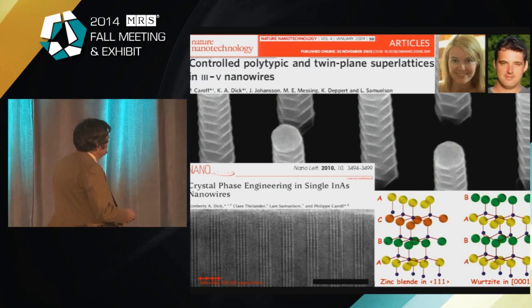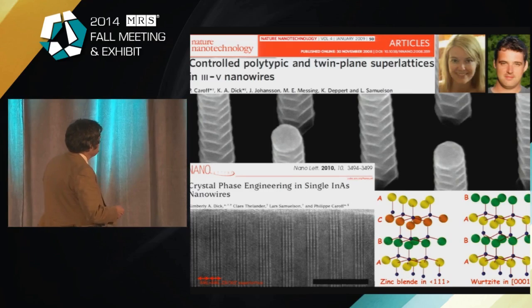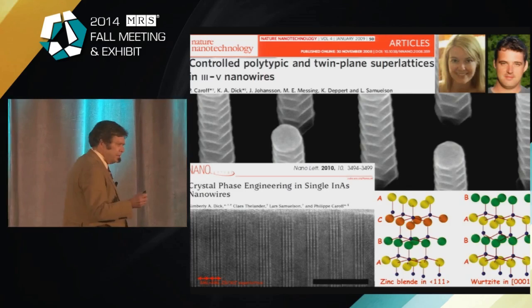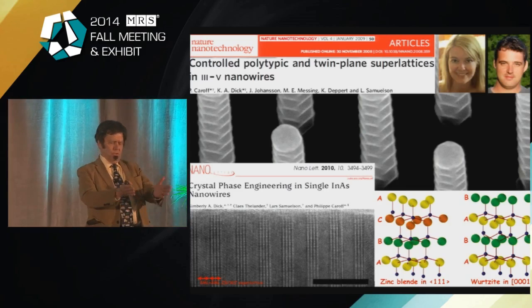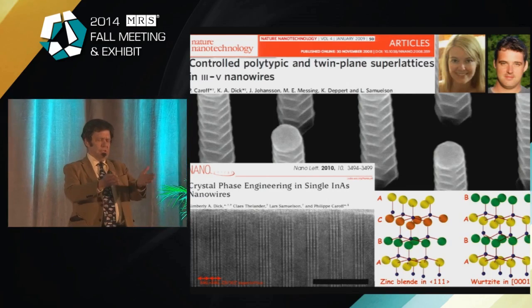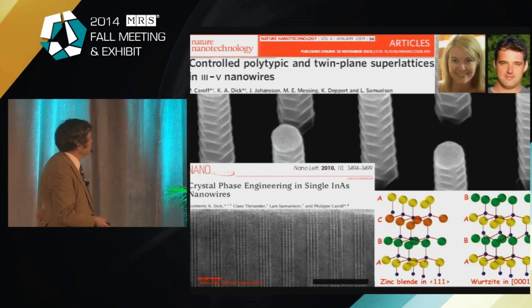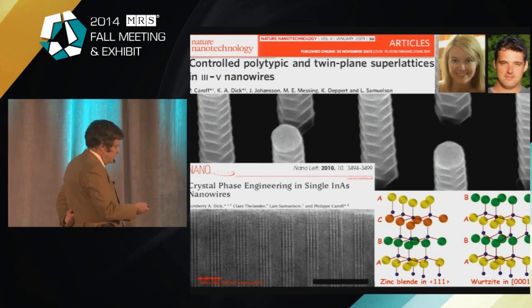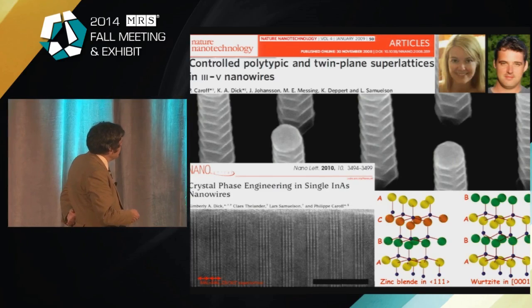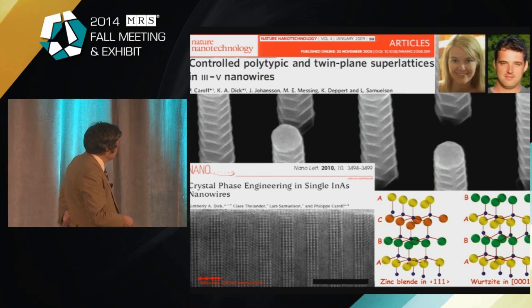This one is actually an example, what you see in the background from this Nature Nanotechnology, is the so-called spontaneous insertion of twin plane superlattices in zinc-blende-grown nanowires. And that has to do with the deformation of the crystalline facets of the crystalline plane interacting with the gold particle. And then there is a spontaneous insertions of rotational twin planes that gives this totem pole type of appearance.